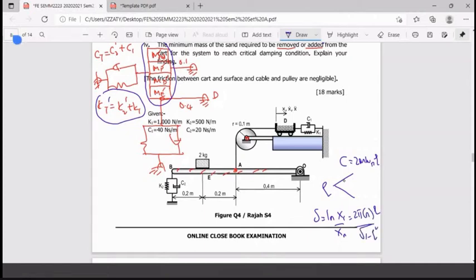But very unfortunately, this one will not provide you any of the parameters, so it cannot be applied. So you use this one. But remember, this is not C but C_T prime, the total one, and this is not m but m_T prime. With the omega n calculated earlier, then you know zeta. And obviously, zeta must lie between this range.